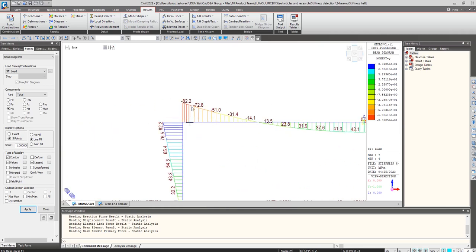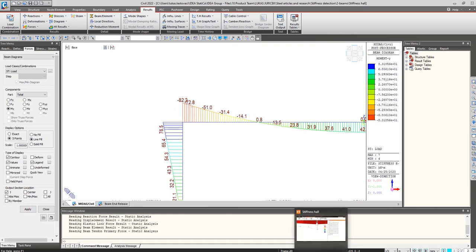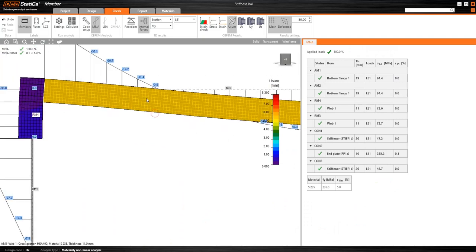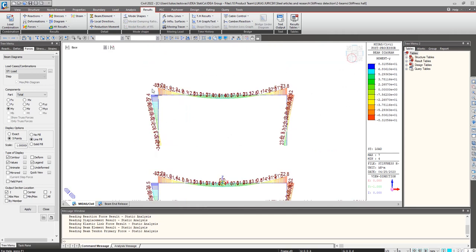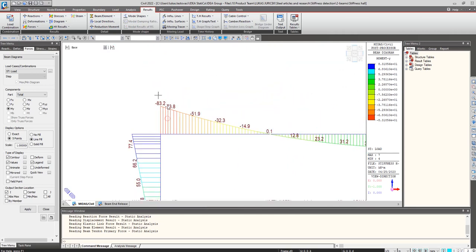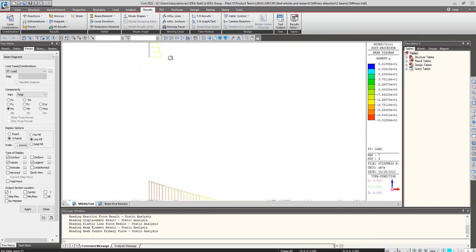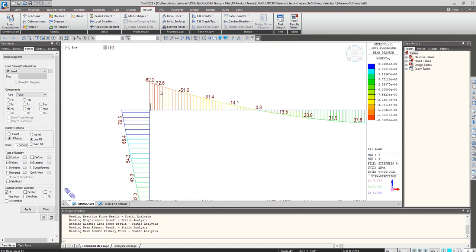This is very important also to check the bending moment in the area close to the frame corner. So if I check it here, I have 70.5, and in my calculation I have 73.8. So this is this value, and this is for linear spring, and for non-linear spring I have 72.8. So you can see the values are almost the same, let's say a 95% comparison.